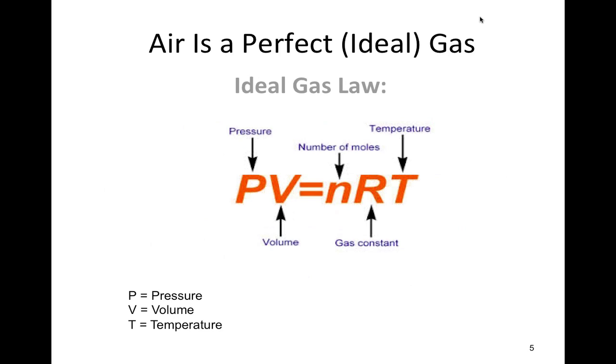Now, the density of air at standard temperature and pressure has a certain quantity. That density is determined by the pressure that it's under. Normally, we're sitting here in air, and it doesn't seem like the air in this space is under pressure because we live in this environment, and this pressure is static pressure. What do we remember about static pressure? It's exerted in all directions. It's in our lungs, pushing out. It's pushing in on our bodies, and so on. So to us, our perception is that we're in zero pressure.